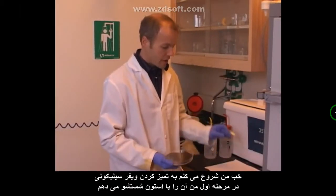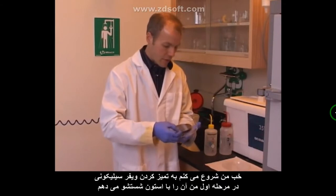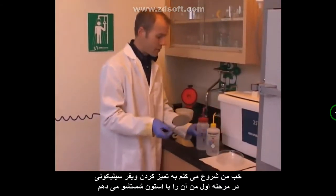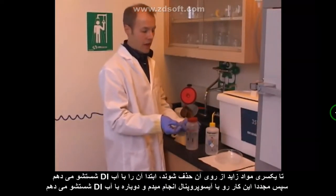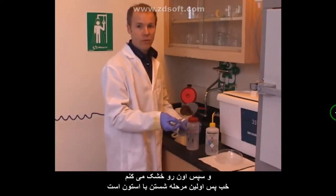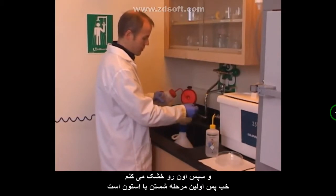So I start with a clean silicon wafer, and I'm going to rinse it first with acetone to remove any impurities, then isopropanol, and finally a distilled deionized water rinse, and then we'll dry it. So the first step is the acetone rinse.